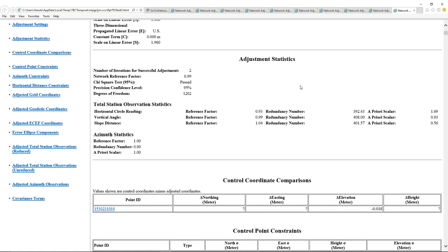So, okay. Richard, the question for Mark was on a purely total station adjustment. Is it correct that you have to constrain the initial setup and azimuth for the initial unconstrained adjustment? Good question. I think the answer would be you'd have to have at least one control point fixed horizontally and some way to orient the network just for the comp engine to work.